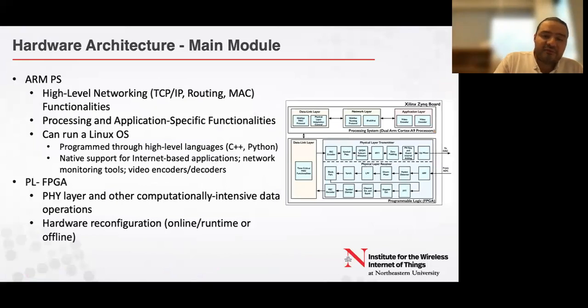One other decision that we have made, which is necessary to be able to run the large bandwidth data that I was explaining before, is that in order to process that data in real time, you have to do most of the physical layer processing in FPGAs, which gives you much more discrete timelines on how you can process data, and also much faster results compared to a general purpose processing system.